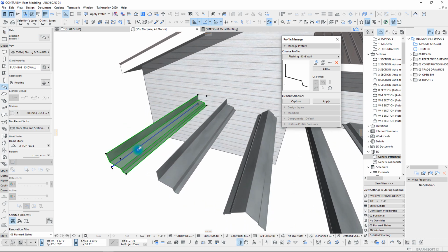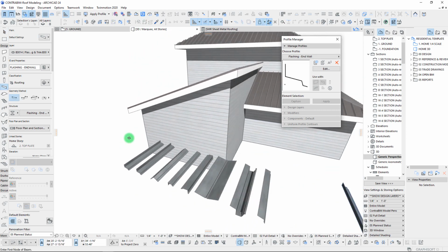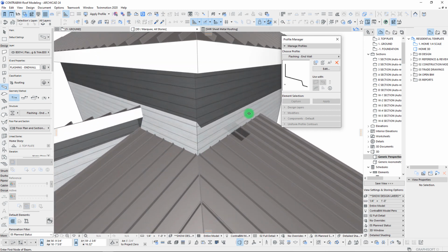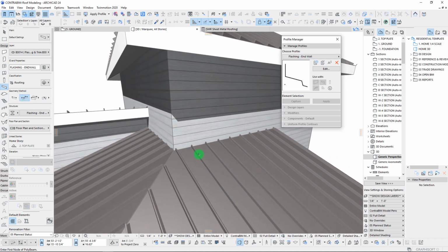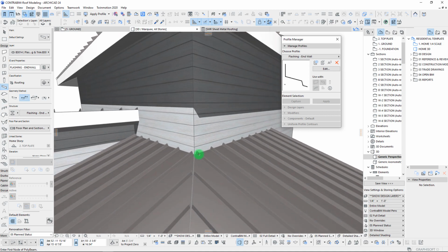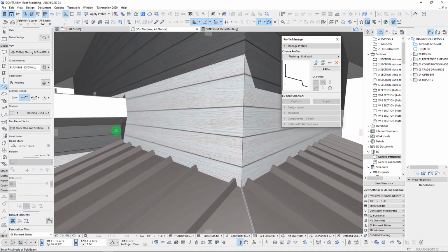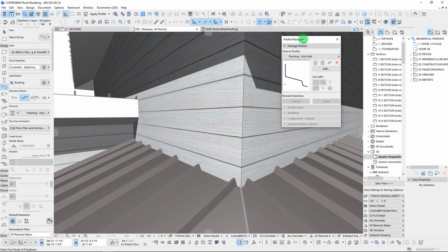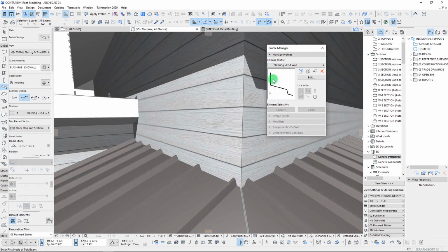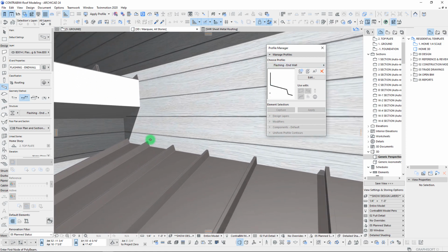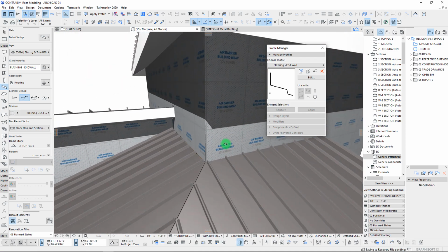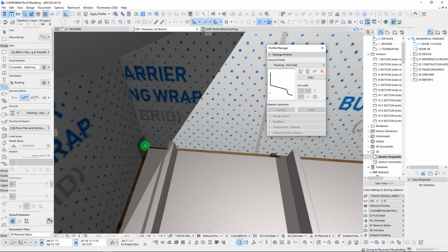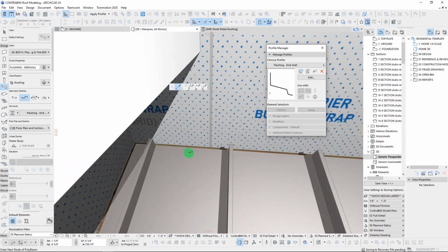First thing here, I'm just going to pick up the settings of this beam. Because we have this corner here, I'm going to change our geometry method to a chained method. One thing with these flashings is often they will be drawn behind the finish, so that if you see the complex profile here, your finish will come down and sit on top of that flashing. So we can peel back our finishes here, turn that off, and that way we can really get in here and start modeling to that particular level.